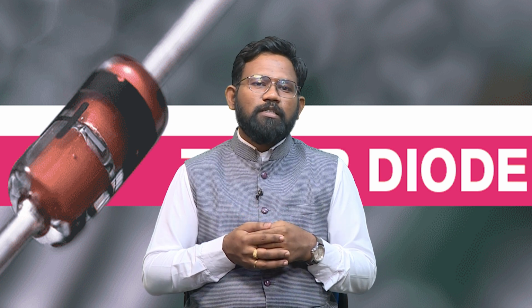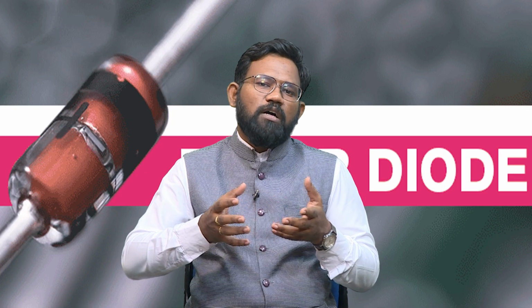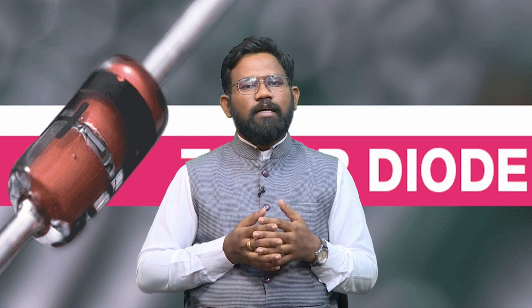Now, the second condition is when the value of V is less than VZ. What happens here is that the diode is in the off state, and it is shown in the figure that the condition here is of open circuit. So, when the diode is in off state, it can be replaced by an open circuit. The following figure shows the off state of the Zener diode, where no current flows through it and the voltage V is less than VZ. So, it is an off state for the Zener diode.